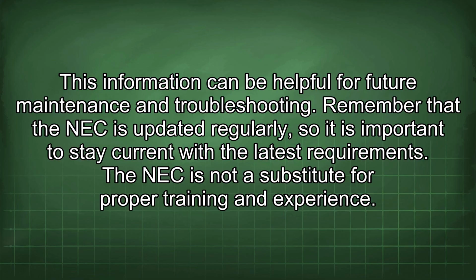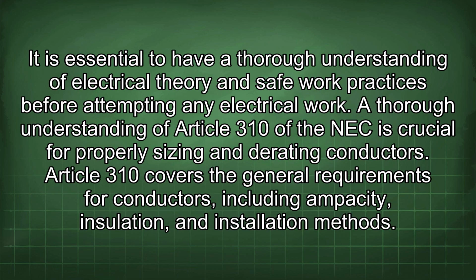The NEC is not a substitute for proper training and experience. It is essential to have a thorough understanding of electrical theory and safe work practices before attempting any electrical work. A thorough understanding of Article 310 of the NEC is crucial for properly sizing and derating conductors. Article 310 covers the general requirements for conductors, including ampacity, insulation, and installation methods.